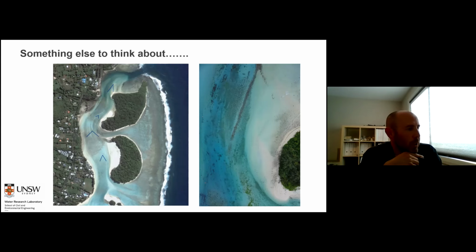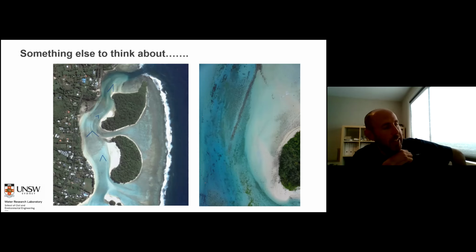But if we look at the southernmost fish trap, it's quite small. It's not taking the full width of the lagoon channel. The flows there are about 1 meter a second when they're really moving, so you probably wouldn't be able to build a structure like that from small rocks and constrain the flow. So they've only blocked or taken off flows from a part of the channel. The second one is located where the lagoon is much broader and shallower, and the flows aren't as powerful, and it's captured most of the main channel flow path.